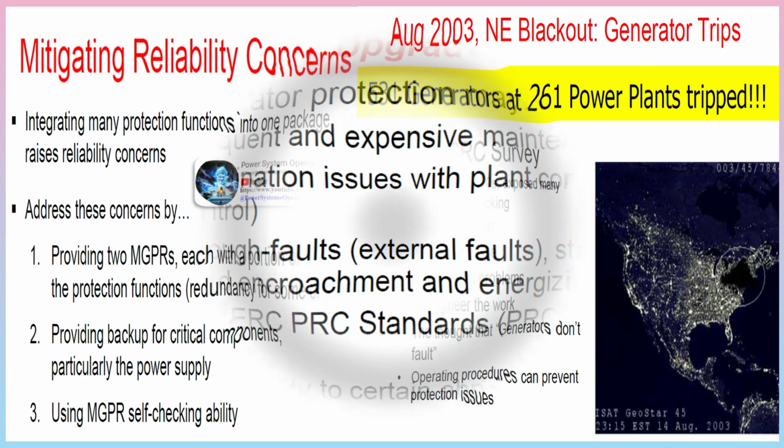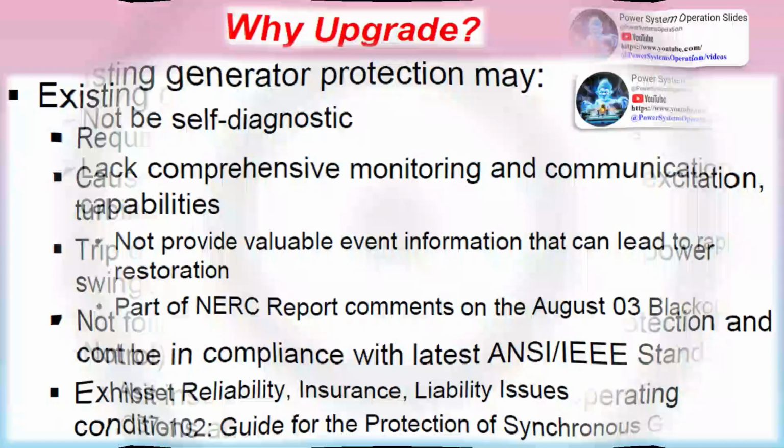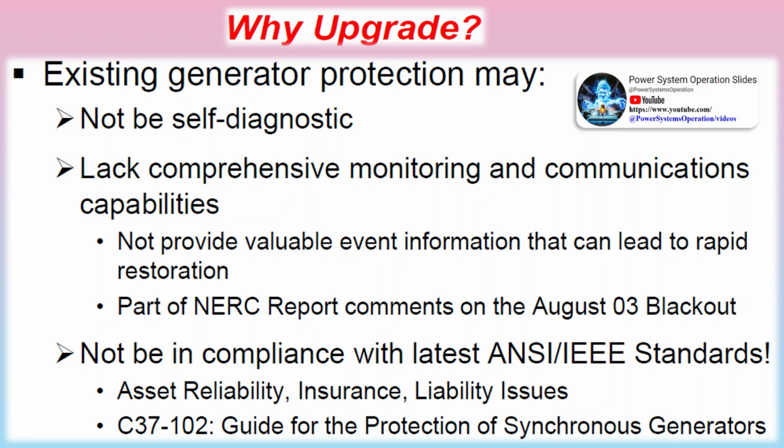The normal IDMT relays would not prove satisfactory because their current settings must be close to the full load and their time settings short if operation is to be obtained, resulting in probable lack of discrimination with other overcurrent relays in the system. Further, the overcurrent relay would most probably operate for loss of field on the machine, disconnecting it prematurely. To overcome this problem, it has become customary to apply an overcurrent relay in combination with an under-voltage relay, the latter relay controlling the fault settings of the former, as shown in the figure below.